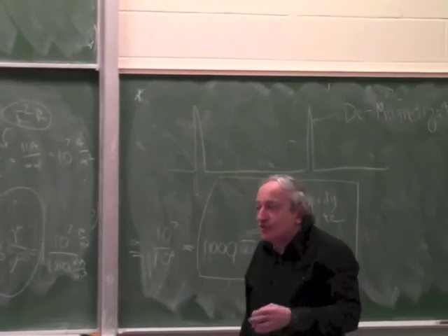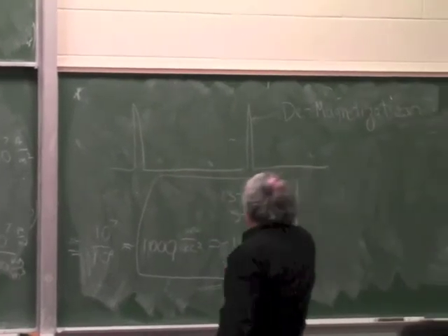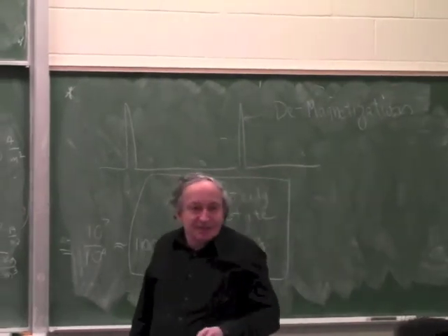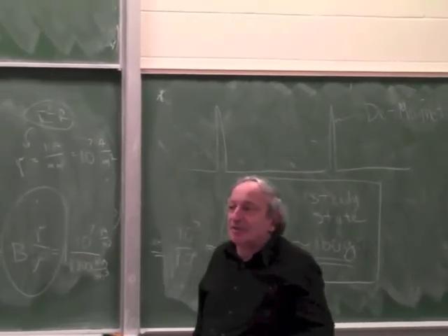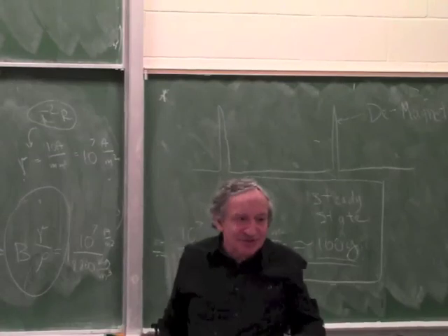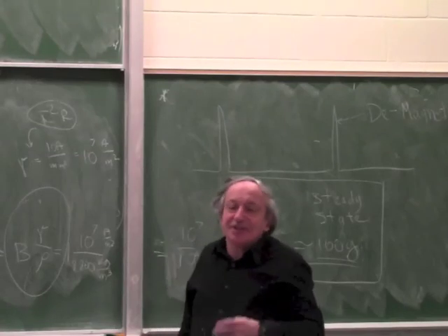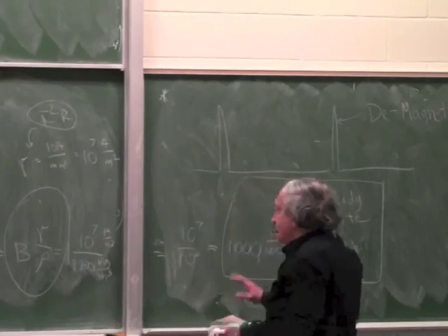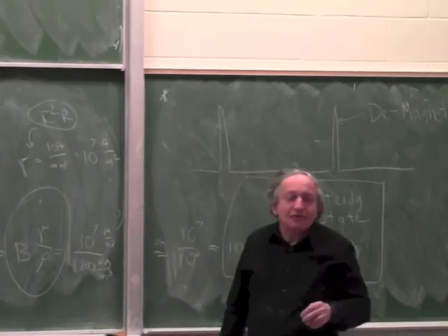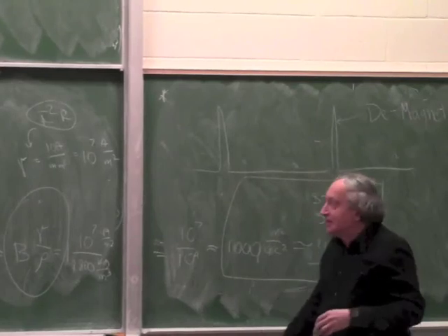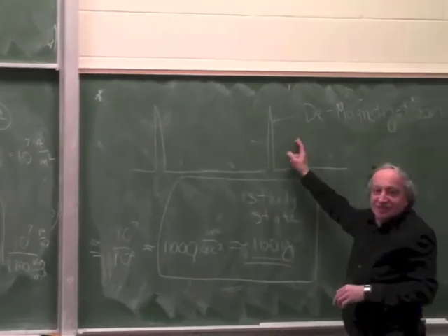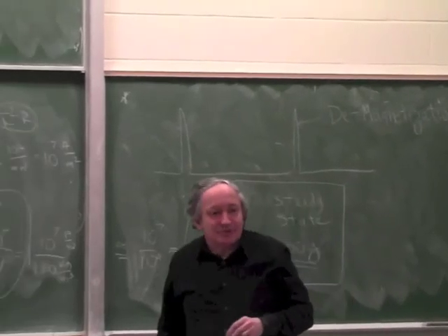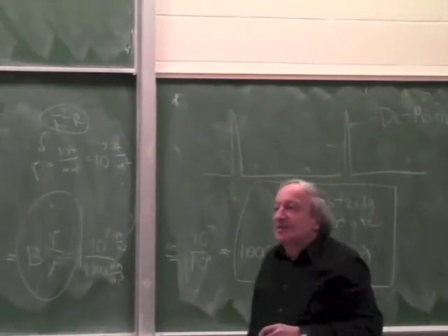If you force cool it, you can increase this number a lot in steady state, and that's being done. That's being done, for example, in very high performance electric motors, in things where you really need the performance and you can't afford the weight, you force cool it. But this whole calculation is without cooling. If you use force cooling, you hit this next limit. Even in steady state, you'll demagnetize. There's many force-cooled electric motors for high performance.